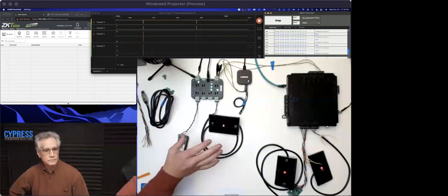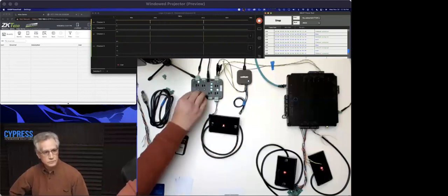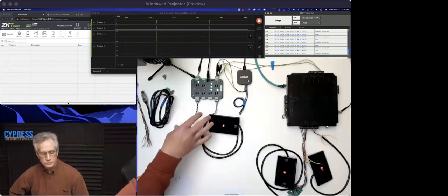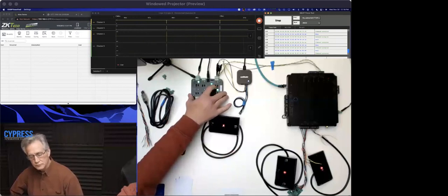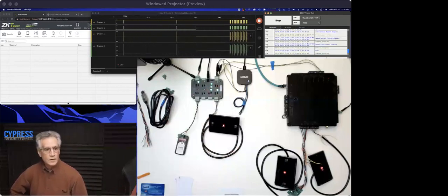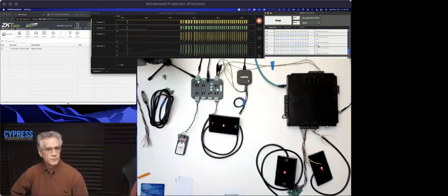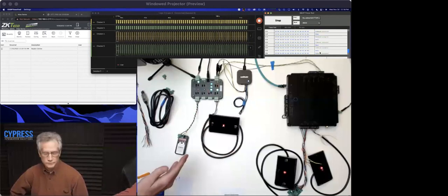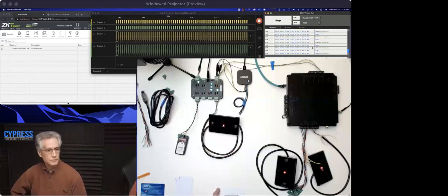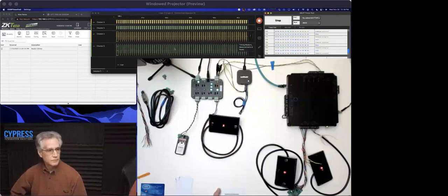Now that we're confident our reader is using the right parameters, we're going to disconnect the comm setter from the hub, the bus, and then we'll go ahead and turn our ACU back on. And then now we see the same thing we just saw with the comm setter and the reader, but only between the panel and the reader, which is the poll and the command, as well as we're seeing a lot more information on the trace over here. So it looks like they're communicating.